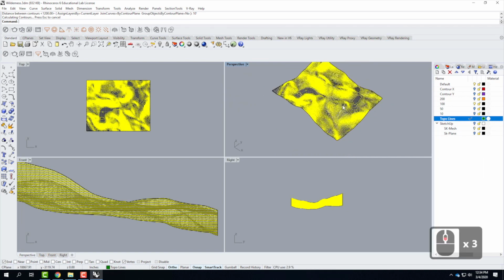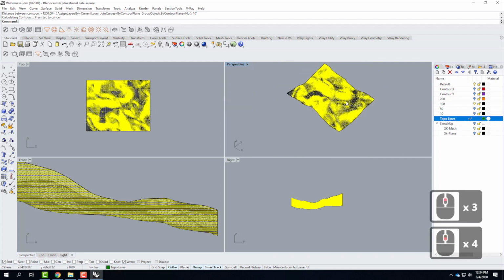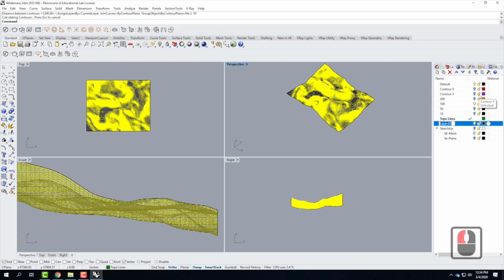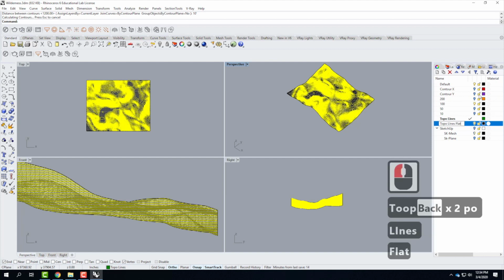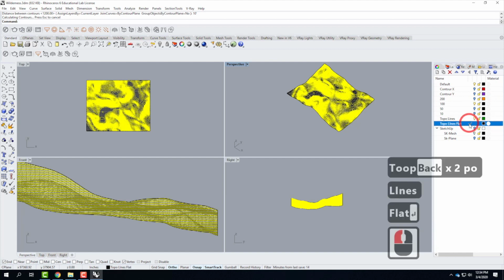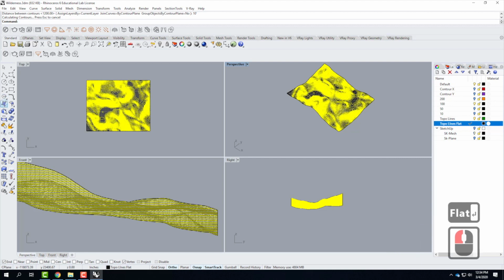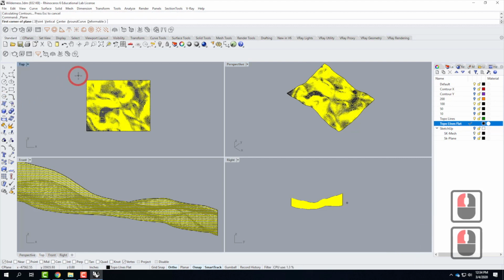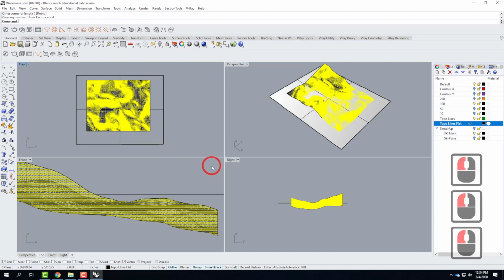There's one last thing that I'll do, and that is that I have my topo lines that are three-dimensional. They're standing up, they're every 10 feet. But what if I wanted to create an actual flat map, where I wanted to go laser cut it or something like that? I could take this one step further and create a new layer called Topo Lines Flat. I'll make that the active layer. I will create a rectangular plane larger than all of those topo lines.